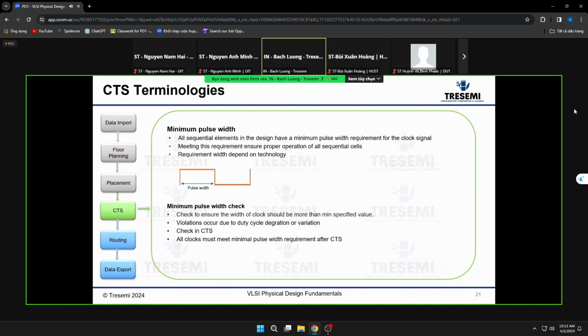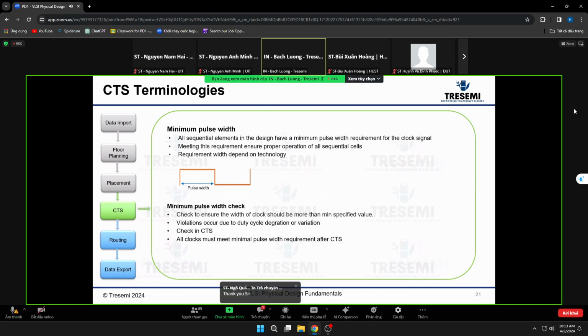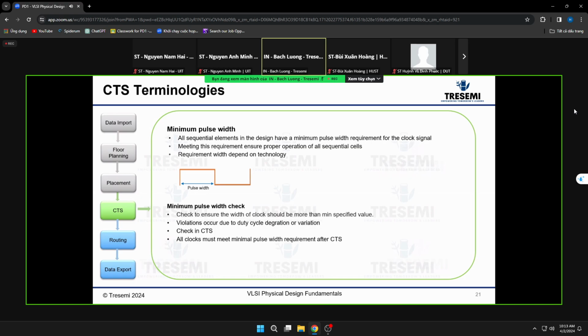We focus on the local, but once you move one level up to the SoC level, and they connect to your design from the same source, the same skew group, then you have an issue: one long, one short.